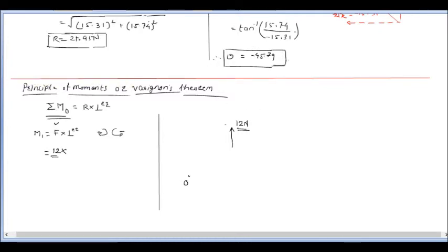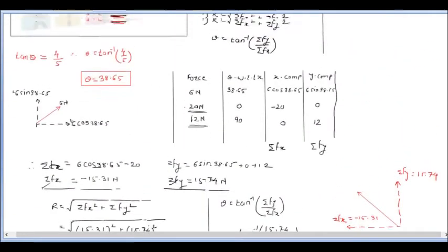So earlier, as I explained, to calculate or find the perpendicular distance, simply extend the line of action of that force, and after extending this line, simply drop a perpendicular onto this line of action from the fixed point. So from the fixed point I am going to drop a perpendicular here. So this is the perpendicular, and I am going to consider this as the link. So the perpendicular distance here, from the diagram we will come to know what that distance is till the 12 Newton